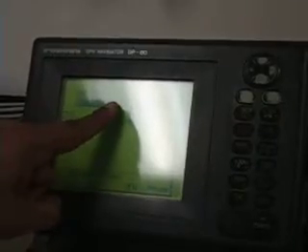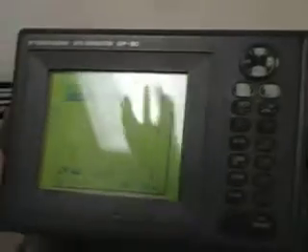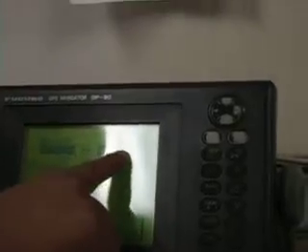Now here the reference station, if I put it automatic and enter, we don't have to do anything. The machine will automatically see which station is nearest to me, where it is getting a very good signal. Which normally we all do, auto. Suppose you have to do it manually, then you have to open this book and do it manually. So highlight manual and write down the station identification number 688. Now because it is 4 digits, you have to write 0688.